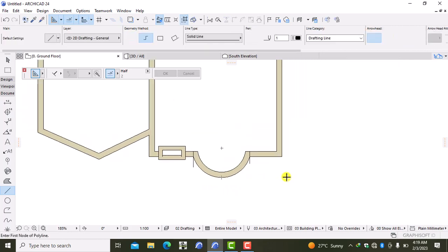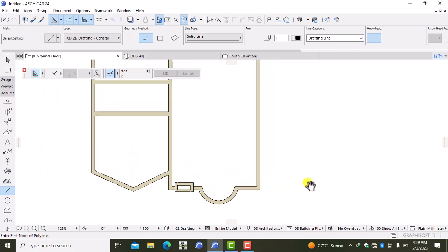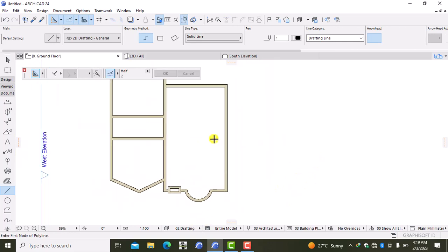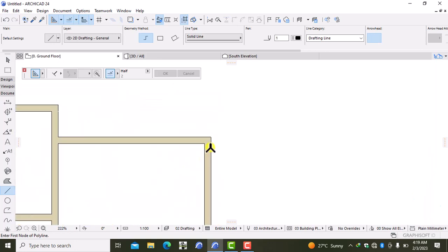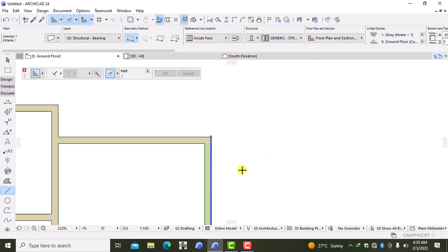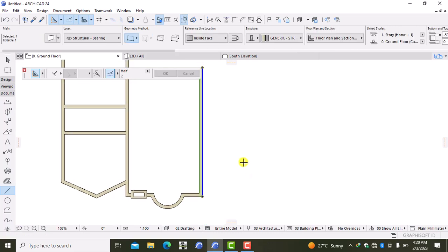Okay, now we have something like that. Also, as I said earlier, we need to get rid of these line tools over here so that you make sure your plan is tidy. From here on, I'm going to drag this particular wall. Pressing shift, selecting this particular wall, I want to drag a copy.